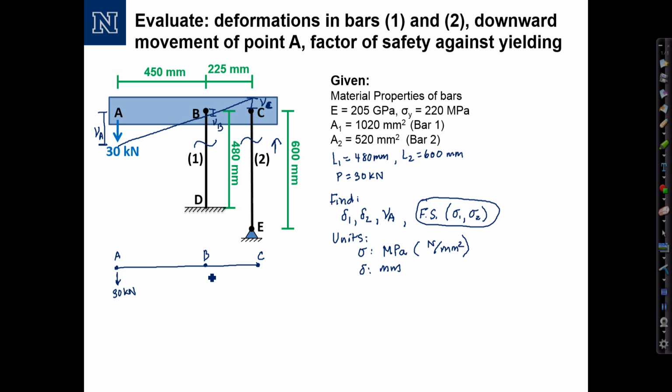One of the conventions that the book generally makes when you have internal forces is to assume they're in tension. Draw them in the tensile direction, and I like this convention. If they're negative, it'll come out in the math. So I'm drawing them downward in tension. If they're in tension, those forces are pulling on the bar.